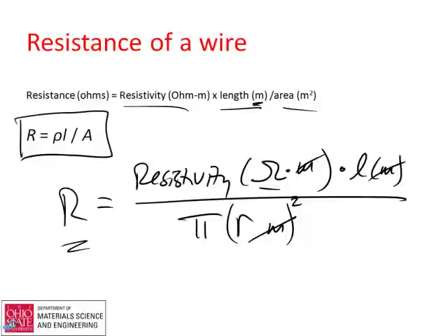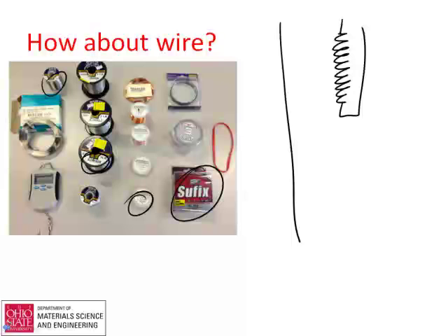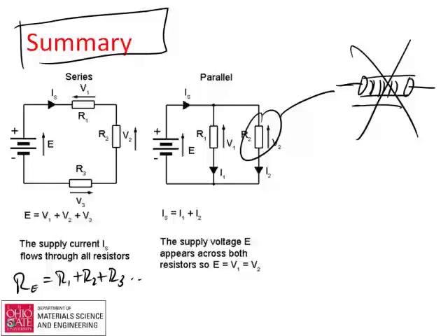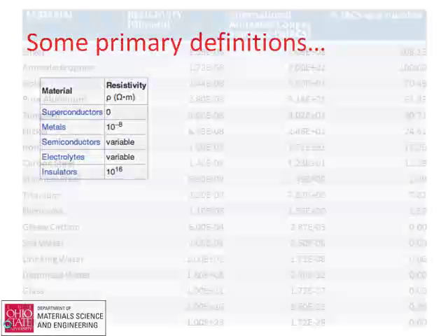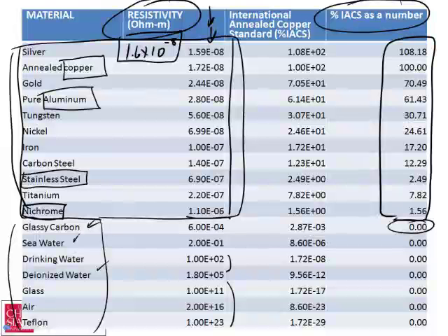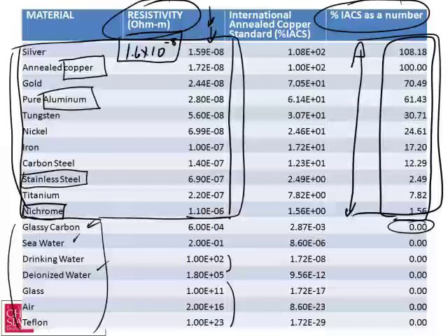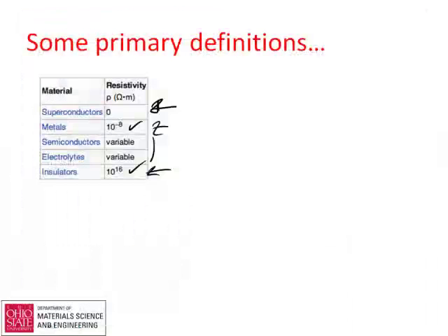And going backwards to what we had before, we've got three primary variables we can change. One is what material we pick, and we can see within metals alone, there's almost a factor of 100 in the resistivity of wires. The other thing we can pick is the length of it, and shape doesn't matter. We can make it into a coil, and we can pick the cross section just by, again, going to McMaster-Carr. I've got all kinds of cross sections I can buy.